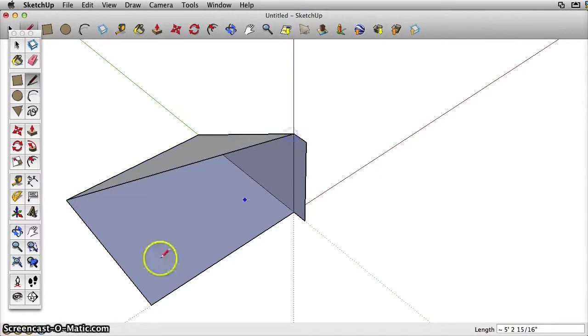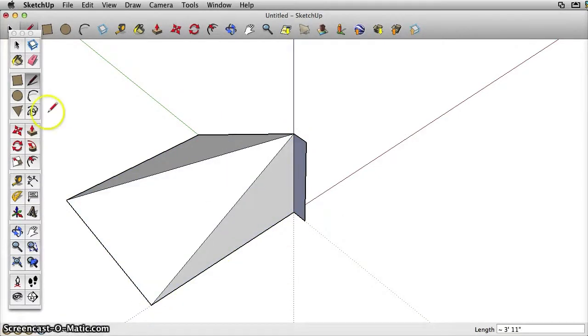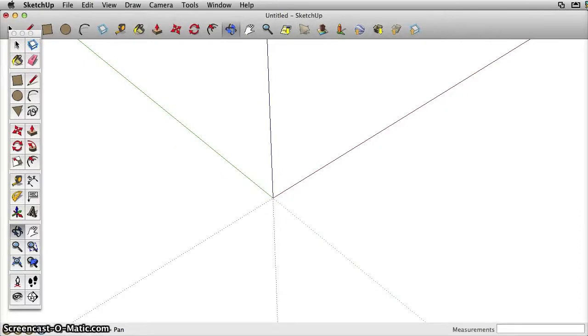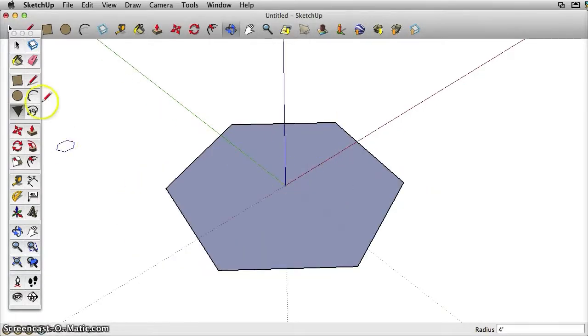I'm closing everything up here. Then just like I did last time, I'm going to hit Command A and delete. The next tool is the hexagon tool, and just like the circle tool, you create your unit of measurement by entering the distance. This tool is really useful for creating equilateral triangles, as you can see here, as there are 6 equilateral triangles in a hexagon.